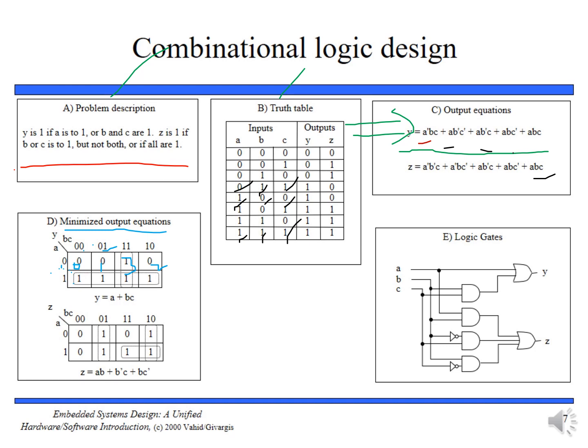Okay, so why do we have 0, 1, 3, 2, not 2, 3? Because we can have only one bit change. So for example, this one is 0 1 1. It means A bar B C. Now writing all these, we can find out the common points.